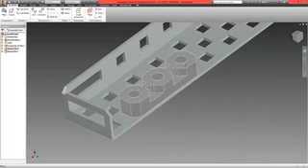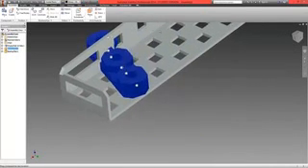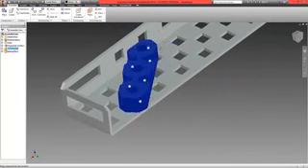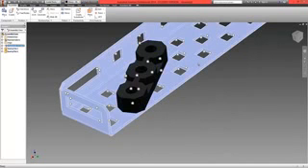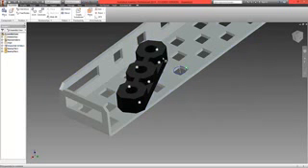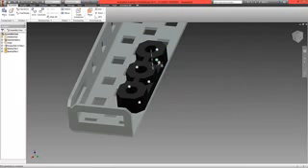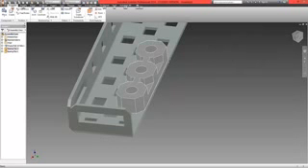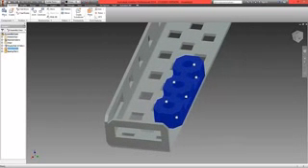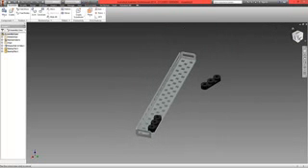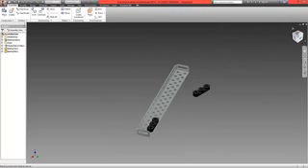Okay, now if we click and hold this, we can see we can drag this part so it's still not fully constrained. What we're going to do now is click back on the metal, select Alt, click on this balloon here, and then match it to its corresponding balloon here. When we now click on the bearing, that should now be fitted in place. Just going to tap the view cube to resize.